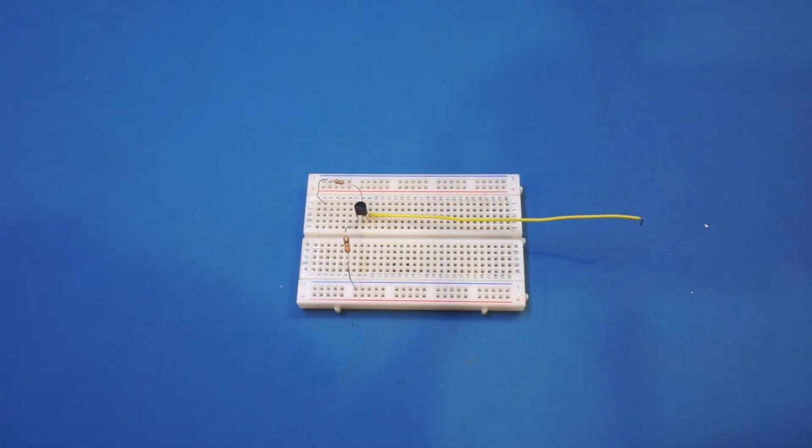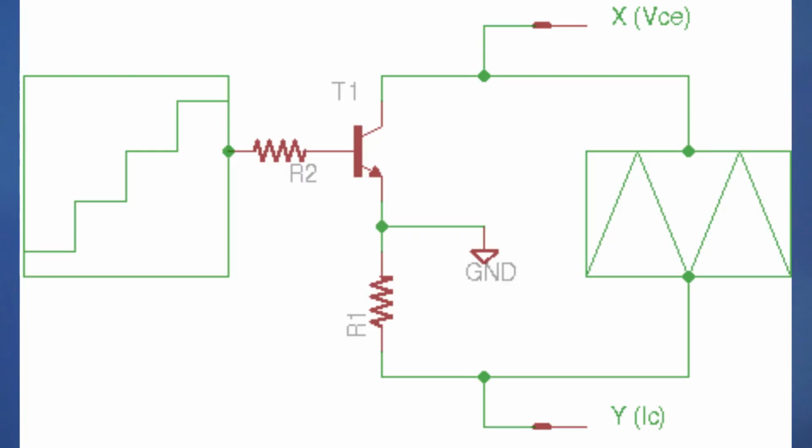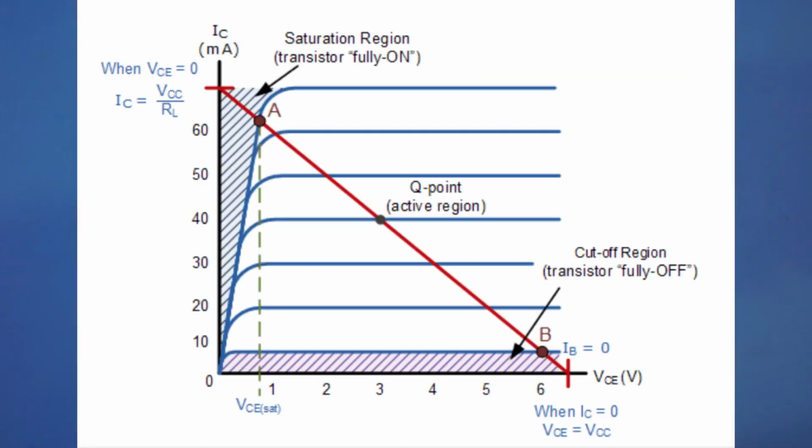The idea behind a curve tracer is fairly simple. For instance, when measuring the collector-emitter voltage versus collector current characteristics, we can step through a few pre-configured base current settings and then use a triangular wave or sawtooth wave to sweep the collector under these different base currents. The resulting curve is the familiar VCE versus IC curve.